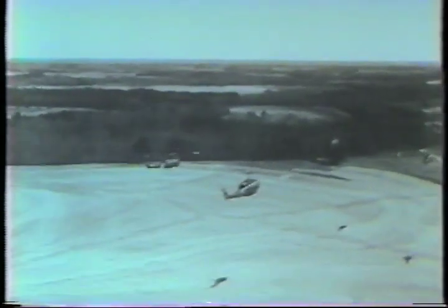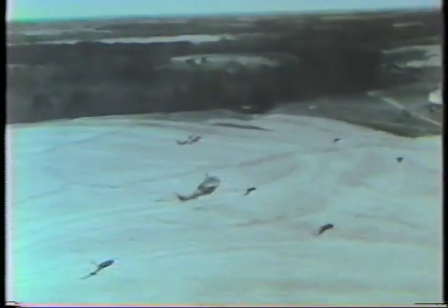Remember the importance of maintaining your position during formation flying. An aircraft should fly on only one other aircraft in the formation. The constant vigilance required to detect any change in altitude, airspeed, or heading of the lead aircraft precludes watching other aircraft. If all aircraft fly correctly on their lead, there will be adequate distance and altitude separation for safe operation. The primary consideration of any aviator is the accomplishment of his assigned mission as safely and expeditiously as possible.